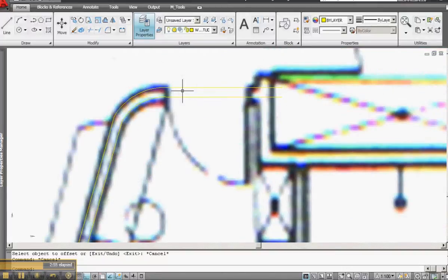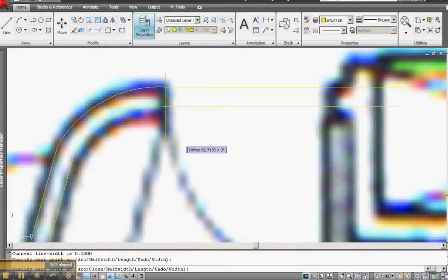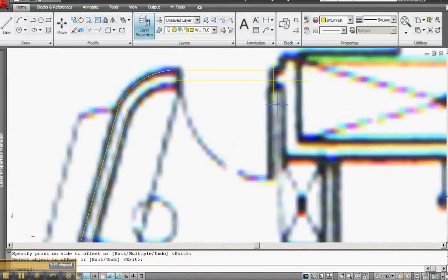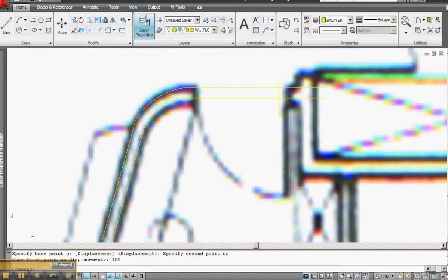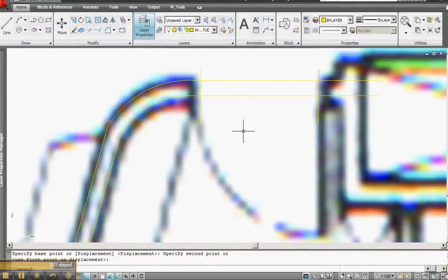and we'll trim out the door. So for a polyline, I'll just start sort of here somewhere, and then I'll offset that. So offset, doors usually 800, 900, we'll do a 900 door, and offset, probably a bit far, actually, because this is a bathroom, it's more likely to be an 800 door, so I'll move that line back 100, so M for move, or you can use this button over here, something like that, and then we can move those around a little bit, something a bit closer to that.